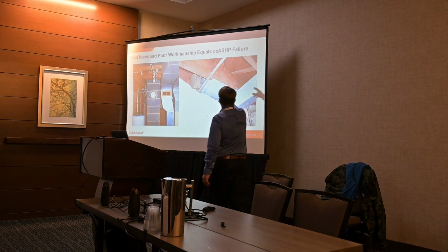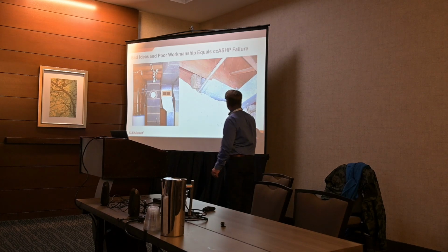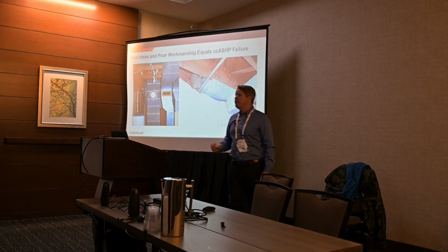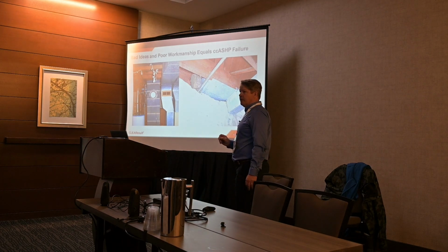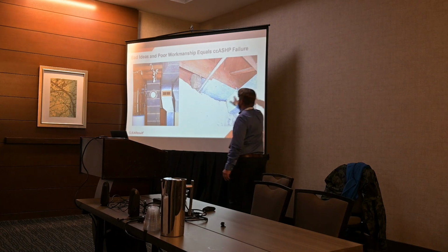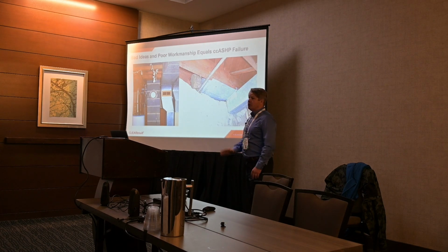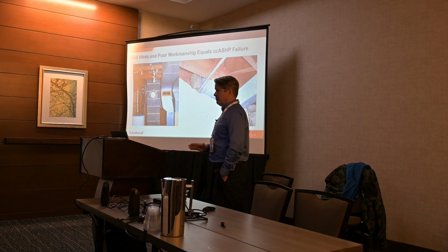You're pulling this in, and the air that's now flowing to the unit, your air source heat pump, that's supposed to be 70 degrees is now 50 degrees. Your air source heat pump has a 30-degree temperature rise. It's supposed to go from 70 to 100, not 50 to 80. You told them the air coming out wouldn't be as hot. You didn't tell them it would be cold, right?